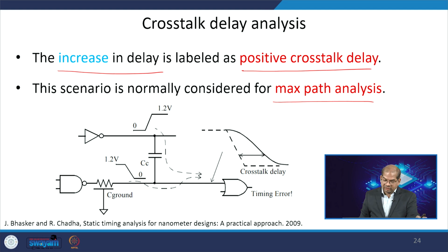Without crosstalk, this is the transition, and this is the transition with crosstalk. So your effective delay increases, and we can use it in case of max path analysis.